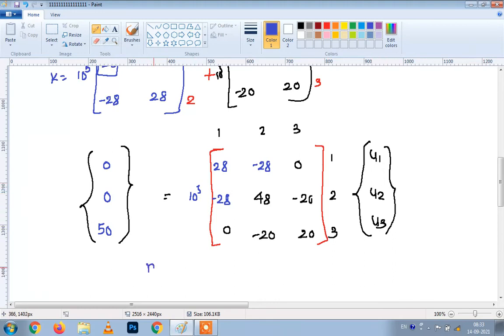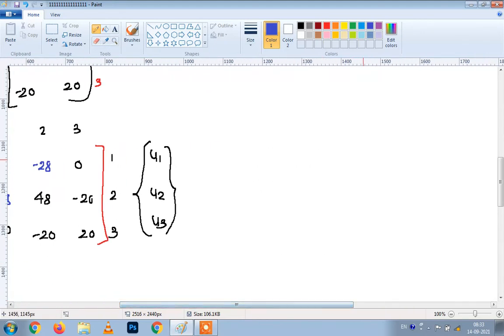Now please focus here. Now we have to use the penalty approach. Just understand the theory first: in the penalty approach, instead of a fixed support, a spring of large stiffness is added. Whenever the stiffness of the spring is very large, the displacement is very minimal and nearly equal to a fixed support. So this is the concept of the penalty approach. Now the large stiffness, in this case, will be like this.